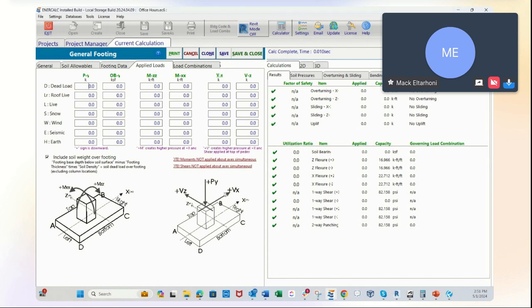You have to orient yourself and your project or specific case, maybe draw it, or just make sure that you understand how the loads all apply. For example, if I have a foundation that has axial load, and then load in the X direction and load in, in this case, the Z direction, you want to make sure those applications are all together.